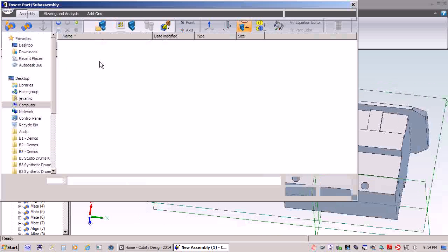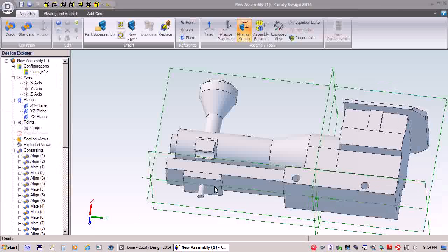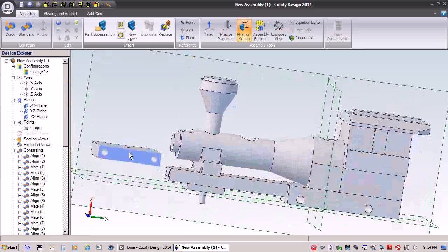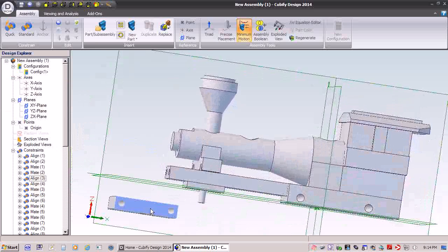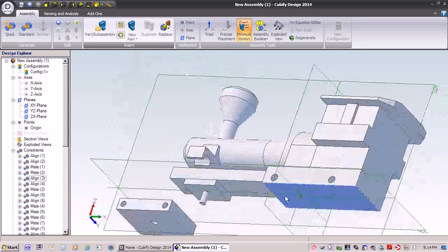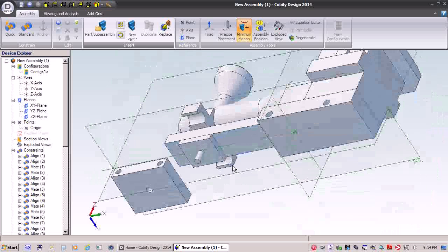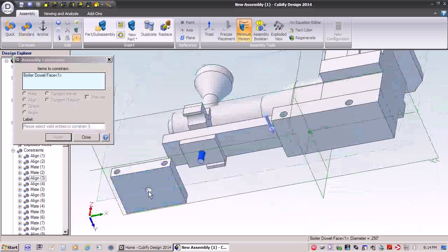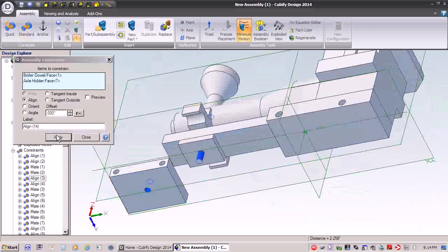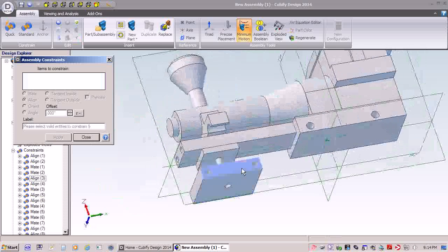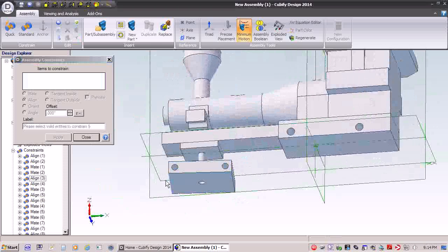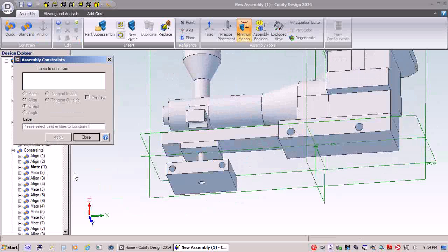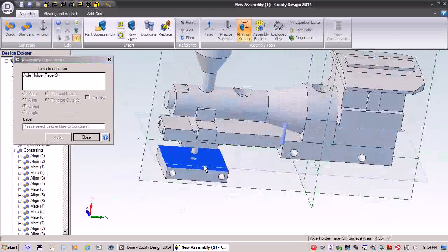Alright, so that's the spacer, and now we've got the holder. The holder is the one that actually has the holes for the axes. I always like to have it on the proper side of the face that it's joining to. Otherwise things get hidden. So again, I've got a rod in the hole, and those get matched up with a line. Again, he's free to spin, so let me do an orient. And the mate to bring them together.